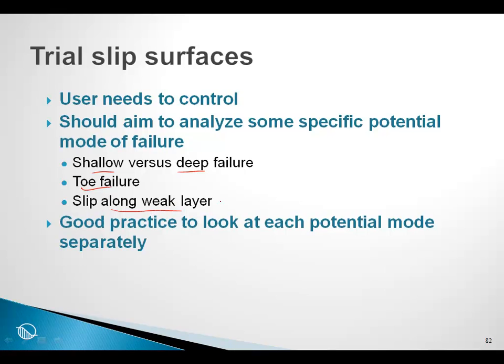It is almost impossible to look at all potential modes of failure with a single set of trial slip surfaces, or for that matter to try and sort out the critical mode of failure with a very wide range of trial slip surfaces that cover many different possibilities. We encourage you to look at each potential mode of failure separately.